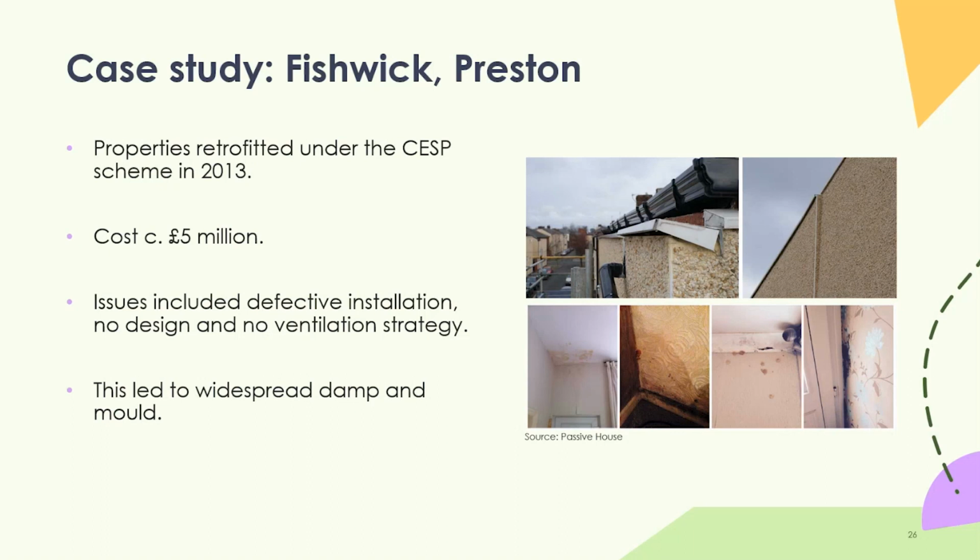And you don't have the risk of water dripping down and getting behind the insulation layer, which is exactly what happened here. It just means that the wall behind the insulation gets soaking wet. The insulation prevents it from drying out, and therefore it migrates back into the house. So you ended up with terrible damp problems on the inside of the house.